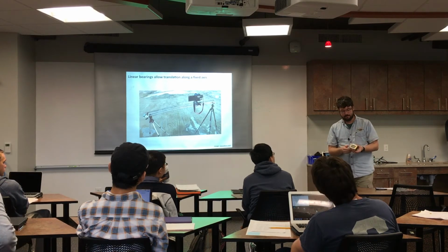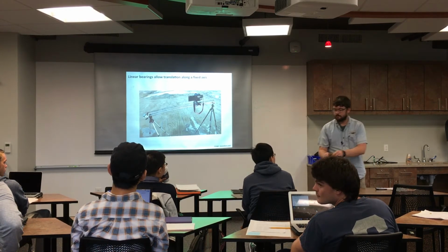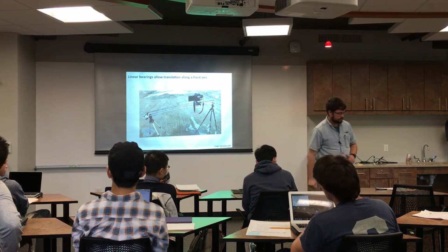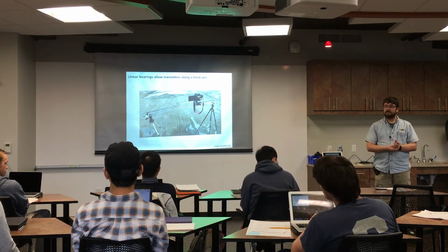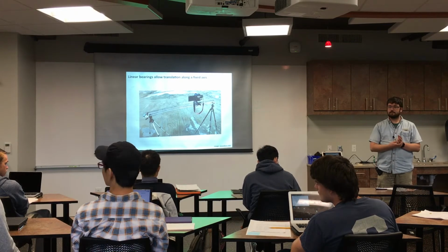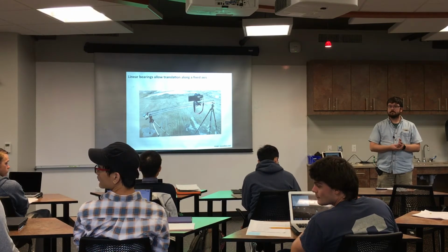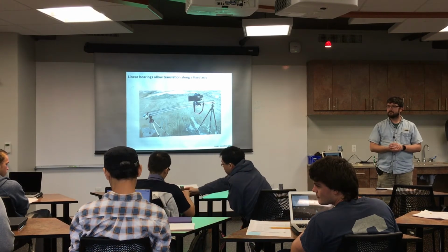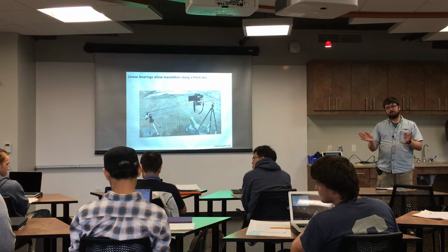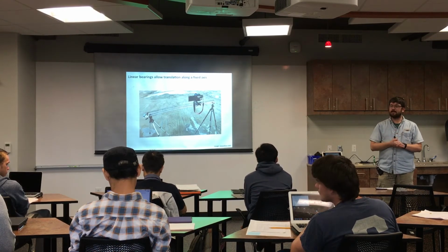A bunch of needles in those, pressure force. It was, I think, designed to handle about 125 kilonewtons. Right. So we used it to turn the double direct shear configuration into a single direct shear, still transmit the load, and in theory, it's more or less frictionless. Right. So it's sort of a linear bearing, but not really.